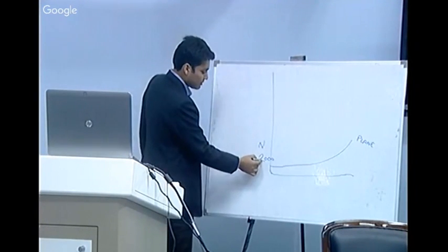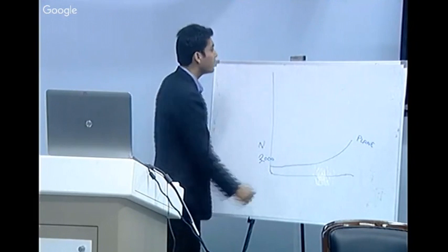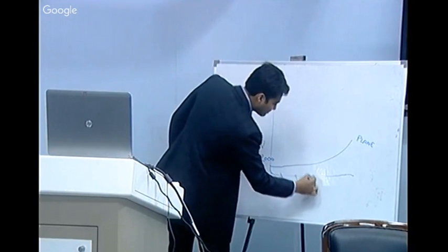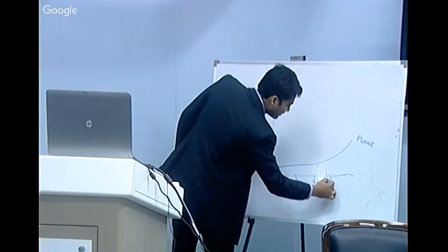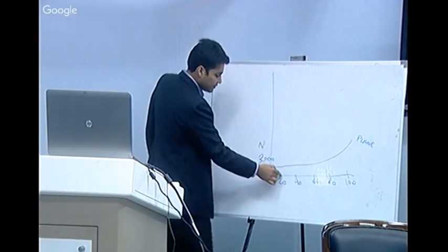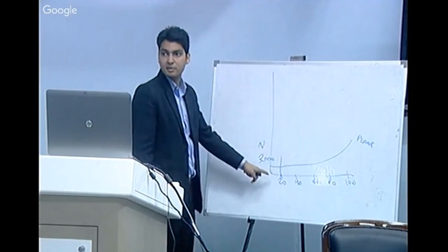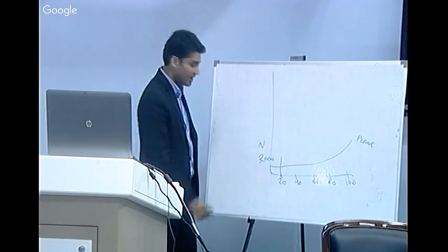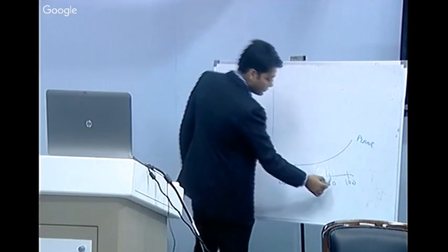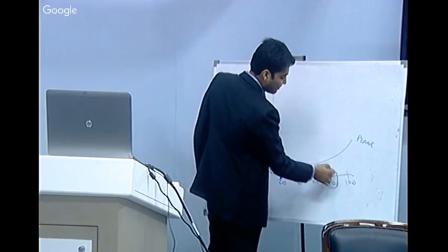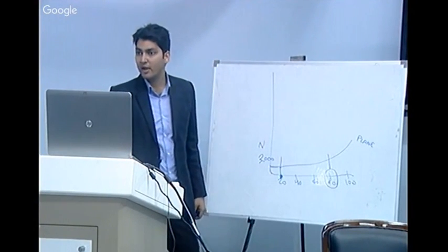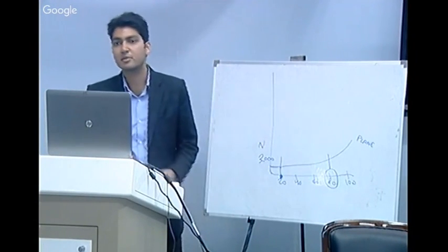These are my torque requirements at 20 km/h, 40 km/h, 60 km/h, 80 km/h, 100 km/h. At 20 km/h my torque requirements are less compared to 80 km/h, where my torque requirements are high. Why? Because the air resistance comes into action.